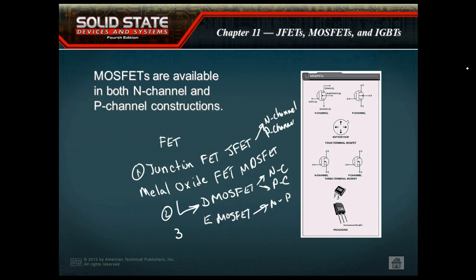So what we do when we make a MOSFET is they start off with what we refer to as a substrate. And a substrate is just a base that we build the MOS transistor in. And then we come in and we create a channel similar to that. Let me do the channel because we've got to be able to separate it.